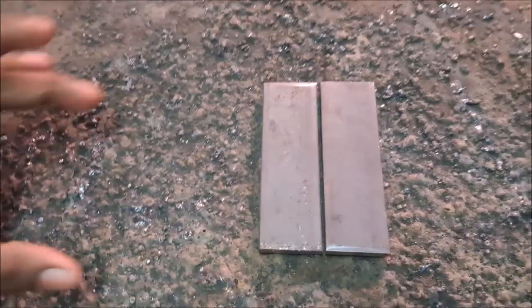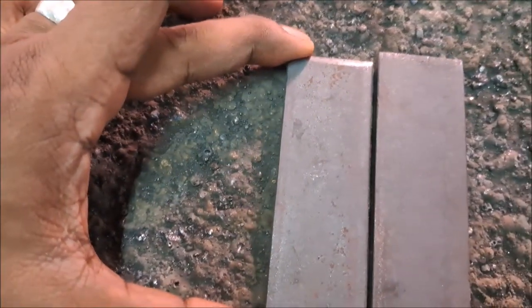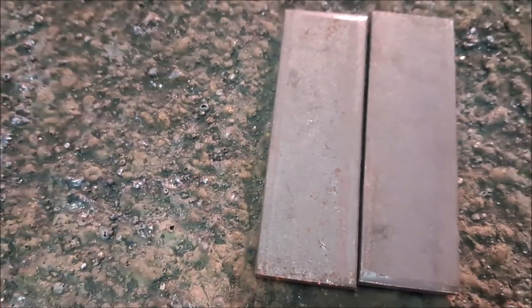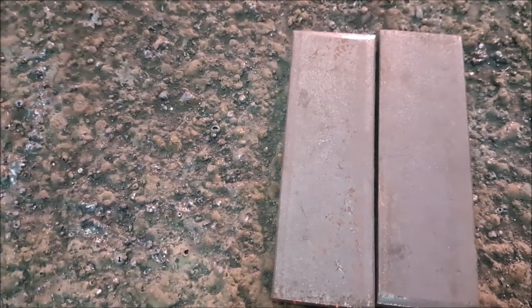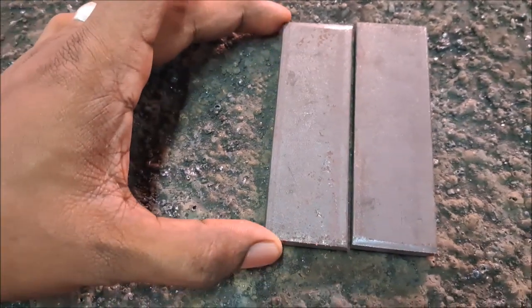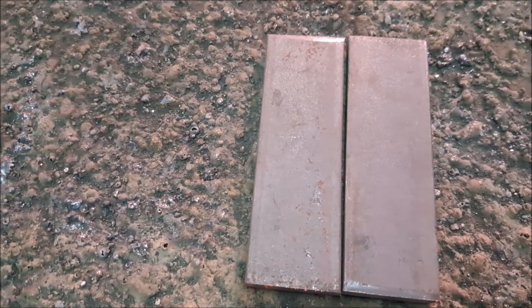When you place the two workpieces, give at least 1 mm or 2 mm approximately to fix the gap. Then, when you do the welding, it will fully penetrate. Otherwise, it's not able to penetrate. So you have to maintain at least approximately 1 mm to 2 mm. Approximately, that is no problem.